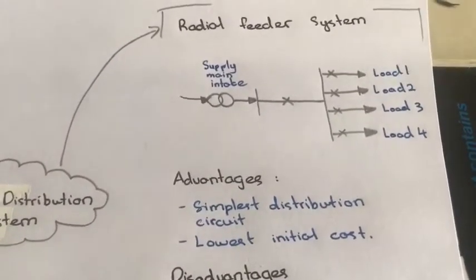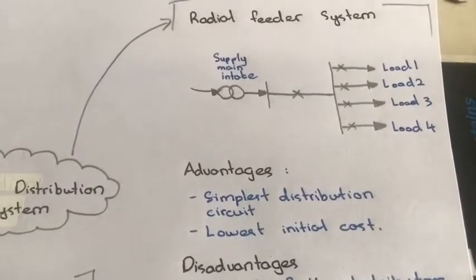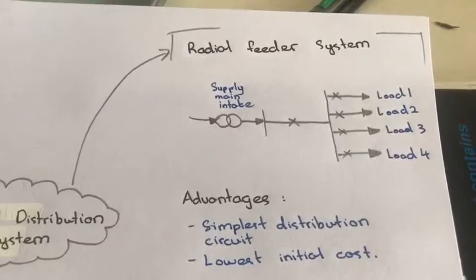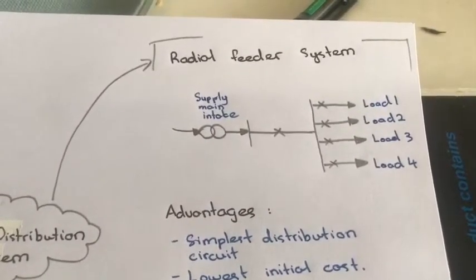Generally, when such a failure occurs, a repair group is dispatched to temporarily re-switch the radial pattern network, transferring the interrupted customers onto another feeder until the damaged element can be repaired.